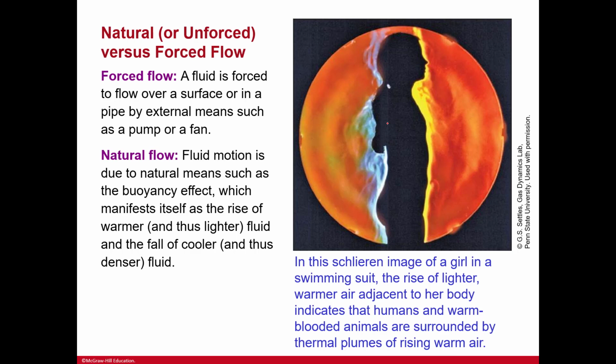A natural flow is where fluid motion is due to natural means, such as the buoyancy effect, which manifests itself as the rise of warmer, thus lighter, fluid, or the fall of cooler, thus denser, fluid. You can think of fog as a good natural flow. It's one that students are really able to picture, because fog forms on colder days when the cool air falls, and then as the temperature rises in the day, it rises, it's lighter,